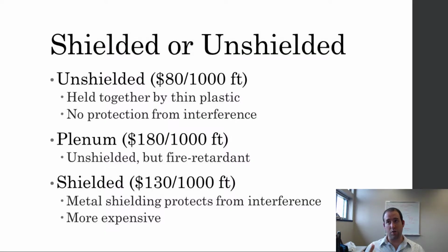In addition to the little bits of insulation and the sheath or the casing that holds the wires together, you have metal that shields those wires from electromagnetic interference. Now, what you probably have is a metal mesh around the entire set of wires, and then a little metal wrap around each pair of wires to prevent them from interfering as much with each other as well.